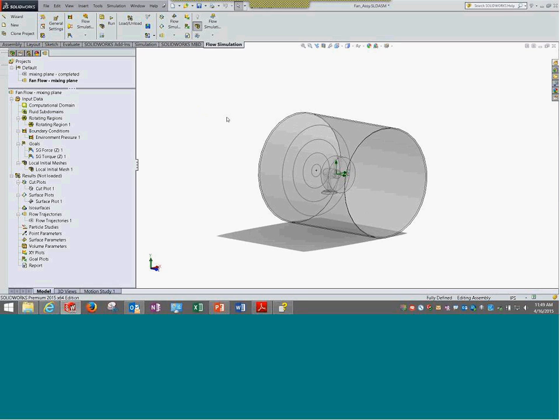One, because we discussed this topic in detail today, deriving the fan curve from these kinds of analysis. So, the fan curve was more of a different pressure drop, what is the velocity or what is the volume flow rate that it can give.